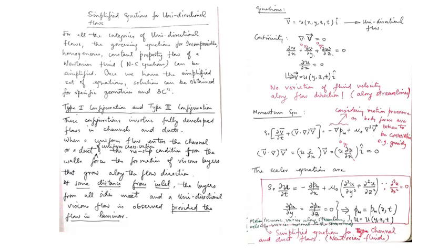So once the body forces are combined with the pressure forces and you are now working with motion pressure, you get these very elegant mathematical results for motion pressure. Del Pm del y is equal to del Pm del z is equal to 0, which implies that motion pressure is not a function of y and z, so it is only a function of x and t. And velocity, we have already shown, u is only a function of the u component, which is the only component, is a function of y, z and t.